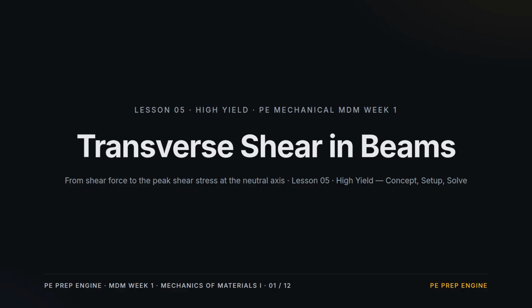Three one-line ideas. Transverse shear stress is VQ over IB. The first moment Q is what carries the geometry, and the stress peaks at the neutral axis, exactly where bending stress is 0. Get those three, and beam shear problems fall out fast.